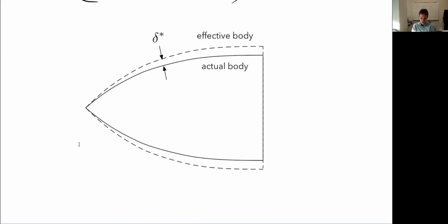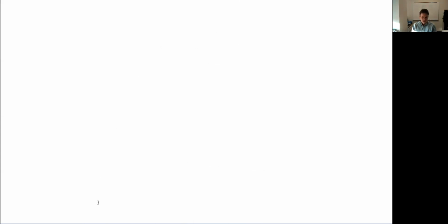Although in practice, we'll usually do something a little bit different because doing it this way is more complicated. It's a little less efficient because if we change the geometry of the body, we have to repanel everything, right? We have to rediscretize, we have to resolve all our influence coefficients. And in 2D, that's not a big deal, but for 3D geometries, that can be problematic, right? And then we have to think about maybe intersections, if I've got a wing body junction, and there are a lot of little details that make this a little more complicated. So we'd actually not like to change our geometry. So instead, we're going to change our boundary condition. And I won't fully derive this because it's in the book, but I want to explain the concept again, which is this.